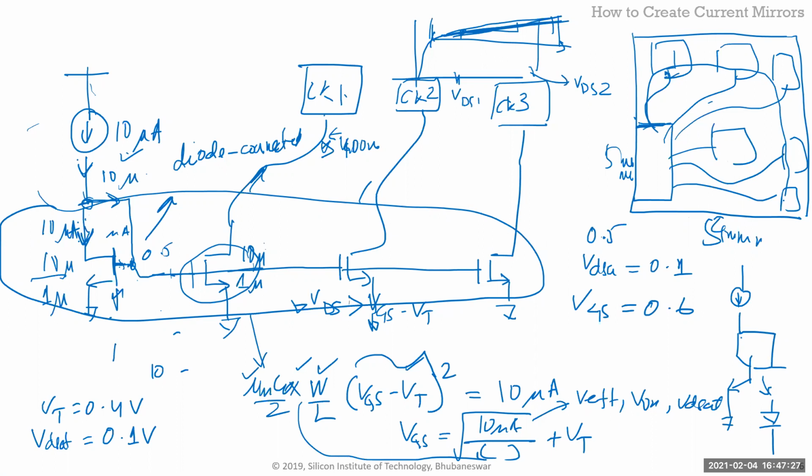Hmm? Routing resistance? Routing wise, yes, you save maybe some routing, but it's not a whole lot. I squared R, what is I squared R? More power? No, no, no, you can't use more power. You're always pumping in the same amount of current. VDS is the same. It's to do with noise coupling and mismatch.